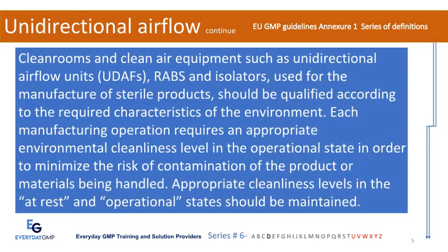In continuation of unidirectional airflow, clean rooms and clean air equipment such as unidirectional airflow units, UDAFs, RABS and isolators, used for the manufacture of sterile products, should be qualified according to the required characteristics of the environment.